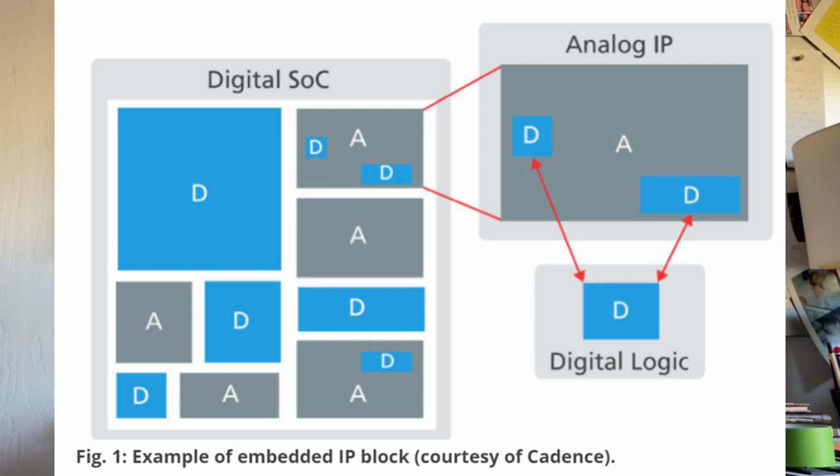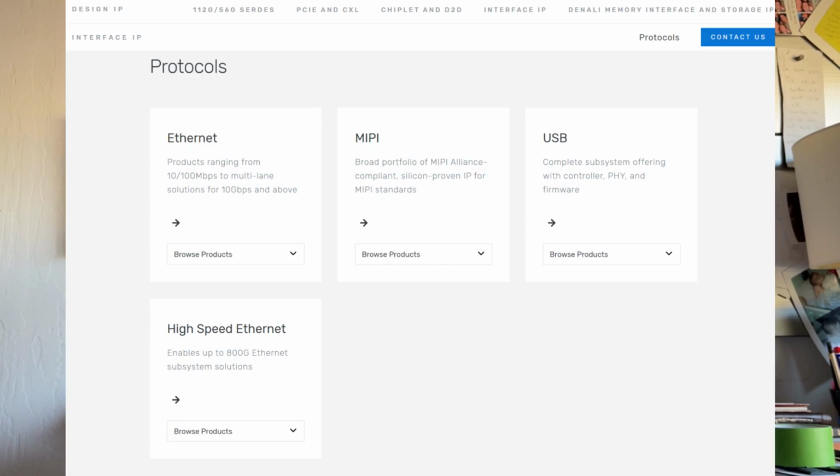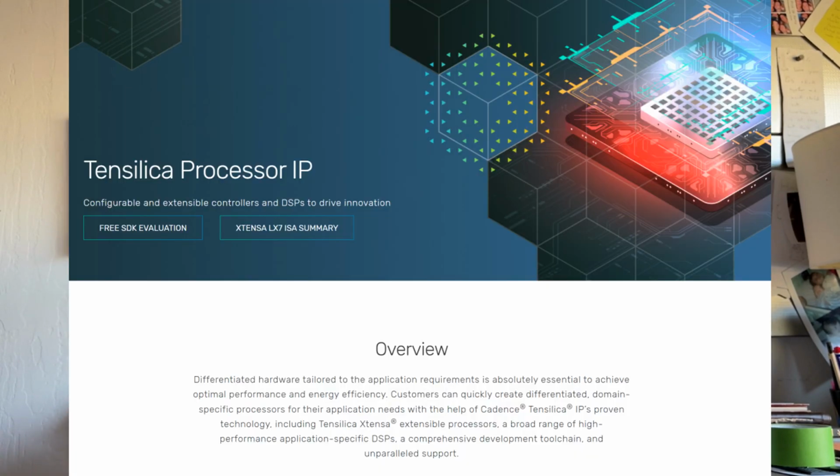You may buy an IP block that is some type of memory, or a peripheral like PCIe, or an IP block for a DSP, a CPU, whatever. You get these blocks, and that allows you to accelerate your design. Then all you need to do is write the Verilog to interconnect those blocks, plus any extra and unique things that you are going to put into your device.